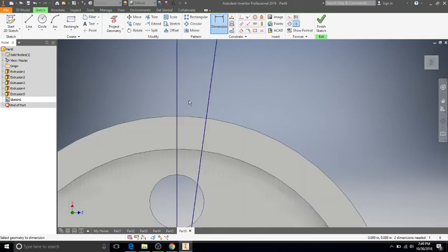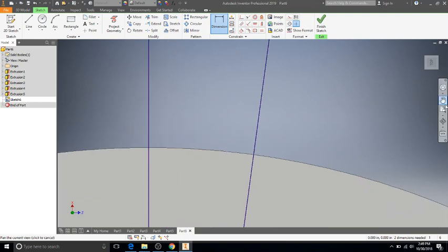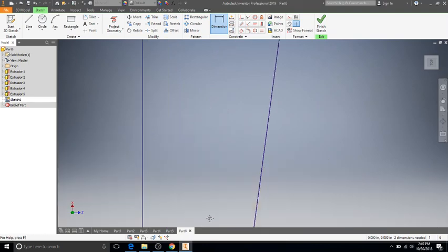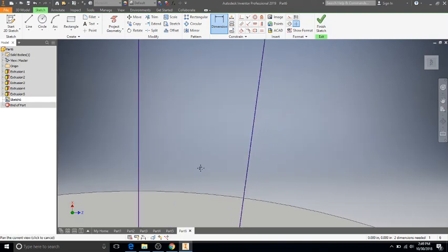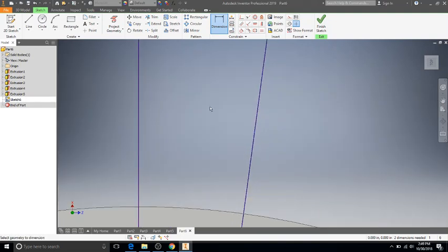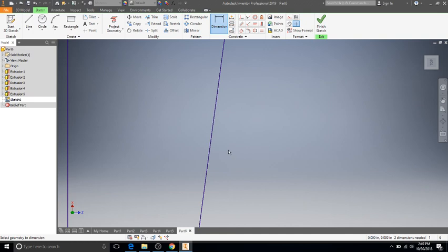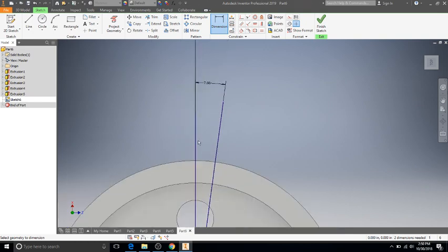So that means I'm going to draw my teeth on the outside here. If I want to draw my teeth for my gear right about here, then we need to fit the tooth over and a gap going across. And this may seem a little bit strange, if you're thinking about the gap being on the right, that means our tooth really, if you would take calipers, you'd be able to measure this out if you actually had a gear you were trying to recreate.